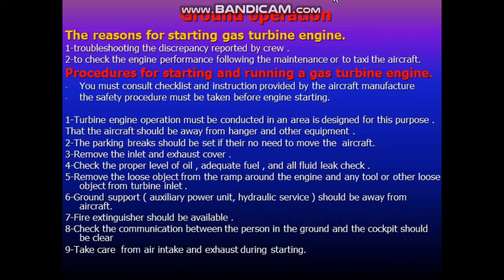The second one, the parking brake should be set if there is no need to move the aircraft. So if we will just start the engine and will not taxi the aircraft, the parking brake should be set on. Number 3, remove the inlet and the exhaust cover. If there is a covering on the inlet and the exhaust, you have to remove it.